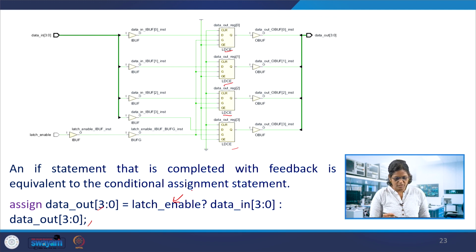So, the latch inference is due to a missing condition, in the else condition or default cases, where the output for every input is missing. That would infer a latch in the sequential logic, that is an accidental latch. If feedback is specified intentionally, that would also infer a latch, that is intentional.